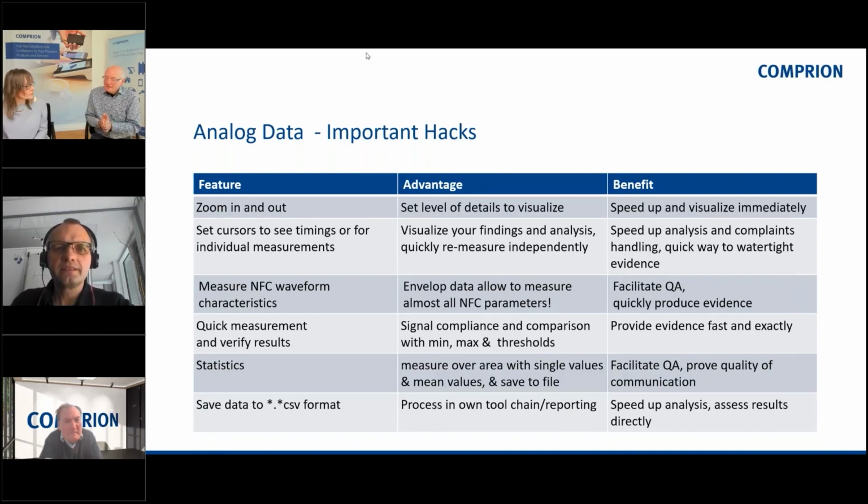I have to trigger to a certain position, so I first use the app to configure my trigger point, and then I have to run this trace, this monitoring, again. Then hopefully we will get exactly the position where we can see, okay, there is our problem, for example distortion of the signal. So it is important to set the trigger point at the correct point in the communication. Of course, maybe you need more trials to find the correct trigger position.